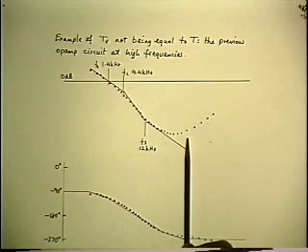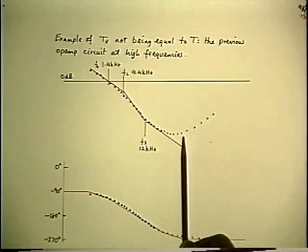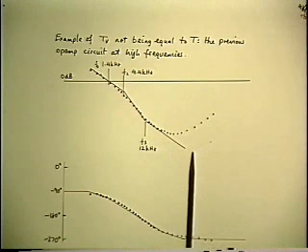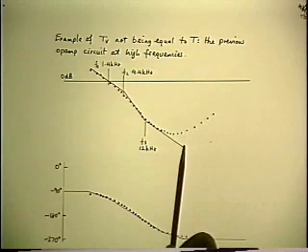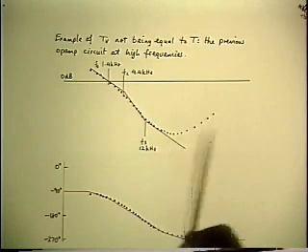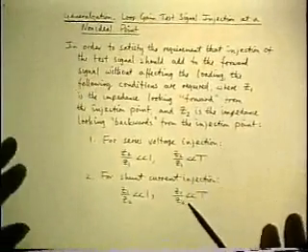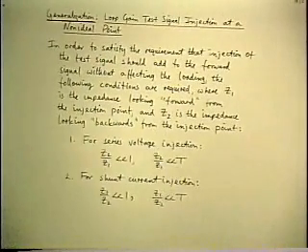And as you see in this example, if that happens, one of the things you need to go and check is, were you measuring the right thing? And the most likely thing that has happened is that your injection point is no longer satisfying those impedance inequalities, because you have to satisfy them at all frequencies because the values change. So when you get a discrepancy over part of the frequency range, that's where you need to check to see whether that ratio is still meeting the necessary condition. So again, summarize that main point.